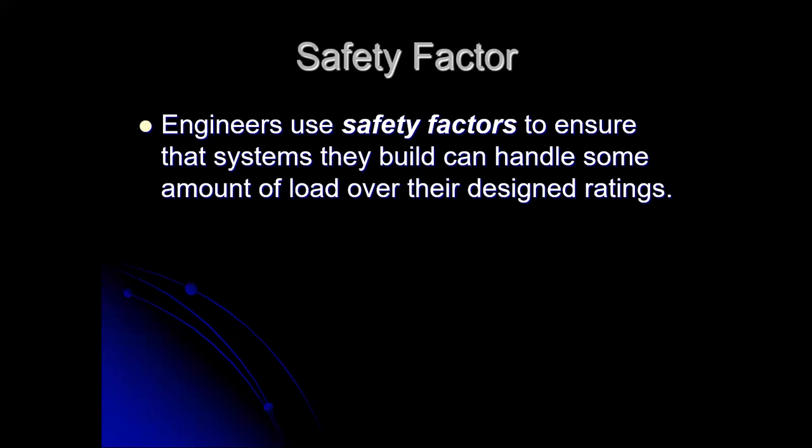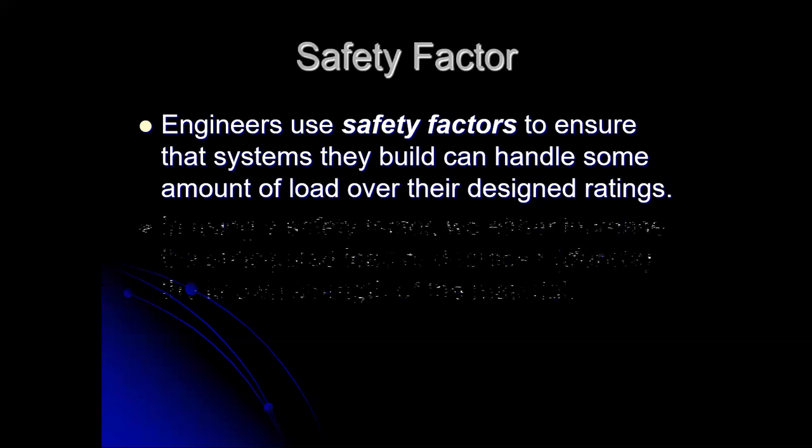But what safety factors do is they cause us to build things bigger than they have to be. We'd use larger areas or more rivets than we really need. And in systems that are sensitive to weight or sensitive to cost, and what engineering system out there isn't sensitive to cost today, we don't want to overbuild things. We don't want to go too far. So there's a lot of art to picking the right safety factor. A lot of times we have it easy because it's specified for us, but in other cases we have to decide what's appropriate and not overkill for the situation.